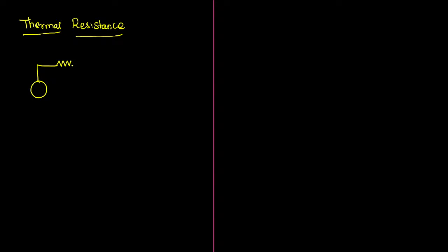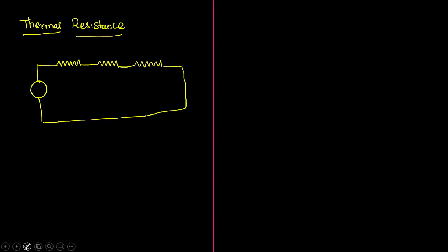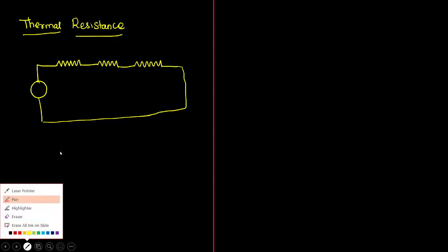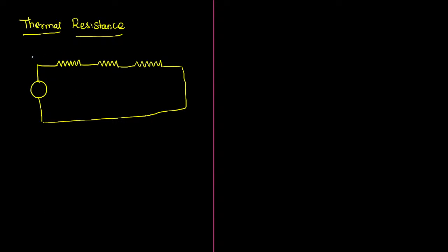So basically during the on state we will be observing the losses, the heat loss, which will be considered in terms of temperature parameters. Let me convert it into a circuit; I need 3 junctions plus the output, which is 4. So I have completed this. Now, what have we considered here? Basically, first you must consider the temperature across the junction, starting from the junction. Then you have to consider the temperature across the case.